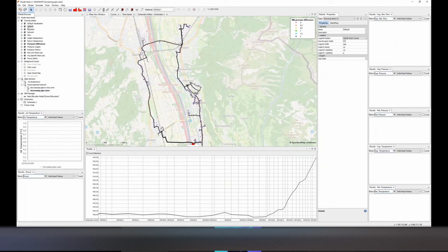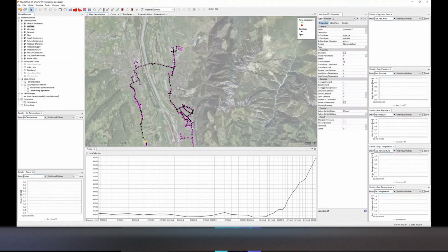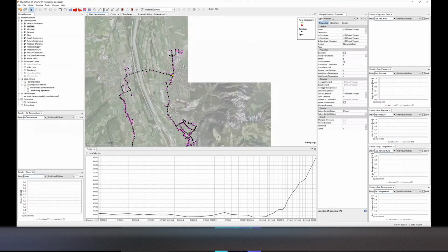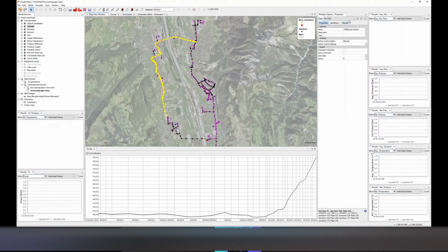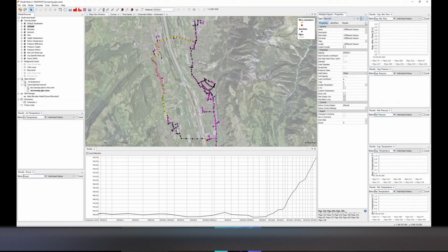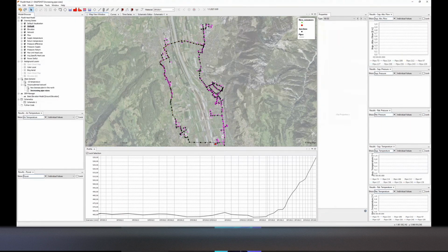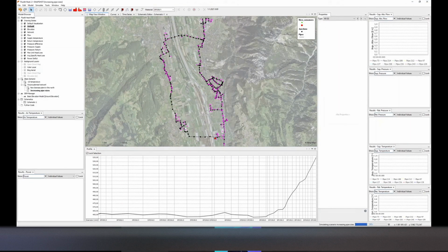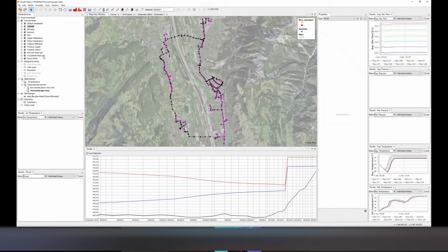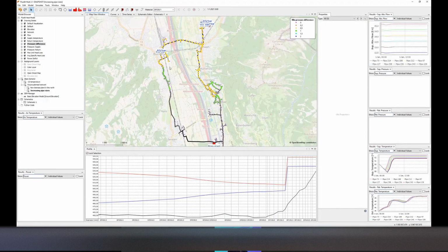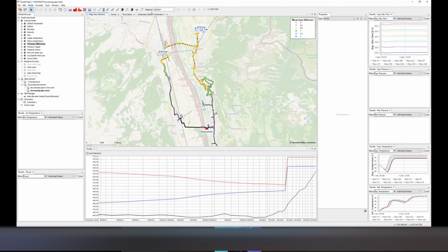So I will change scenario and mass select two components, and I can just get all the components between them, and with mass selection, change all of these pipes into 250 inner or nominal diameter. So the diameter is now 263. Let's simulate the model again and see if we have managed to solve most of our problems.